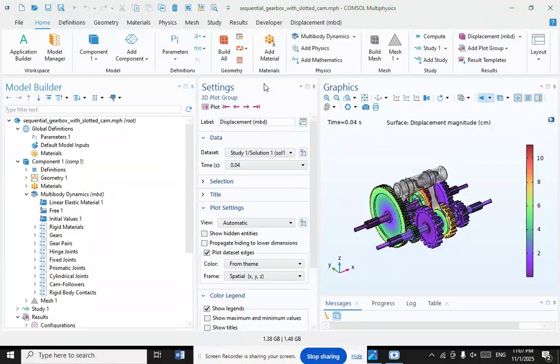In most automobiles, the gear stick is located on the floor between the driver and the front passenger. But some cars have a gear stick that is mounted to the steering column or the center console. The movement of the gear stick is transferred via solid linkage or cables to the selector forks within the transmission.